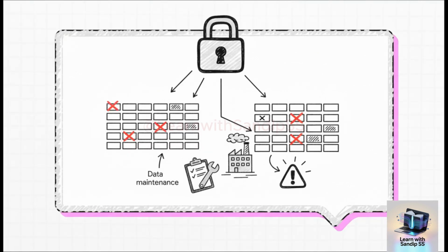And here is the massive pitfall you have to avoid. Just imagine you have, say, 10,000 materials already in your system. If you suddenly make a field mandatory, the system might not let you save any changes to those old records until you fill in that new data for all 10,000 of them. You see the problem? You have to plan for this and do your data cleanup before you make the change live.